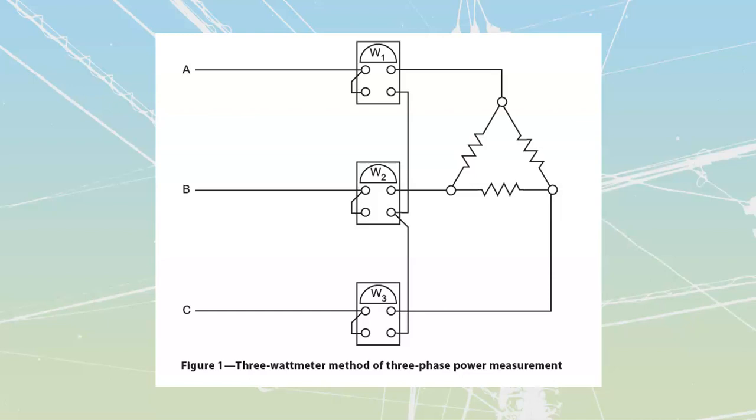There are also a lot of really good power logging components out there that you would be able to run everything through. If you have a large amount of current that you're trying to measure, you would also do that through the use of CTs, current transformers, to knock it down from the large amount of current to something that would be usable for us. But we're going to take a look at our connections.